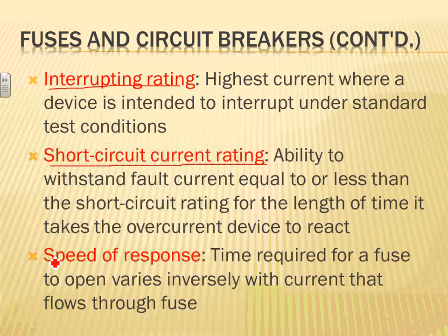And then the speed of response for the overcurrent detection device. The speed of response for the overcurrent detection device will be the decisive factor of how much arc flash, arc blast, and damage to your equipment you are going to encounter upon the existence of a ground fault or short circuit. How fast is your circuit breaker going to trip? Is it a fast acting fuse? Is it a time delay fuse? That's where the whole coordination becomes a well coordinated system versus a not well coordinated system, in terms of safety and in terms of survivability of the system.